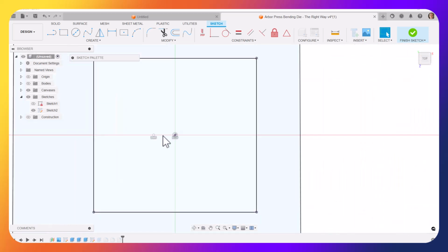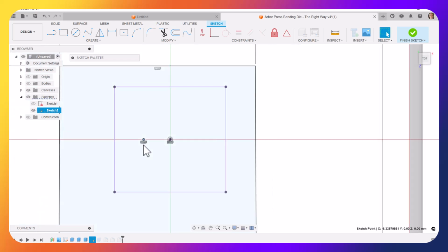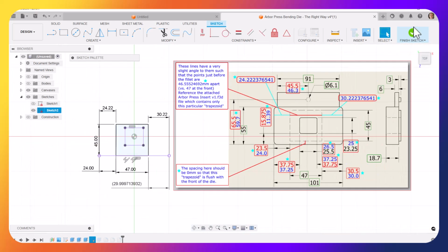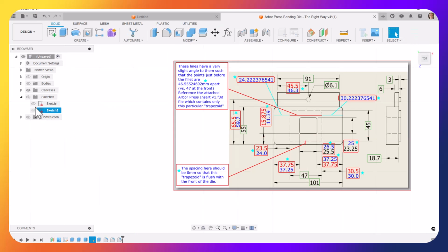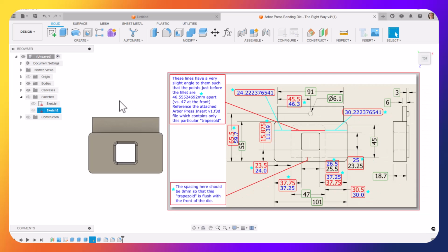Okay, so there was a construction line here that was used earlier to locate that 3.5 millimeters over. So I'll delete that, and now we see the lock symbol. Everything is fully defined. So make sure that your sketches are fully defined when you complete your editing process.